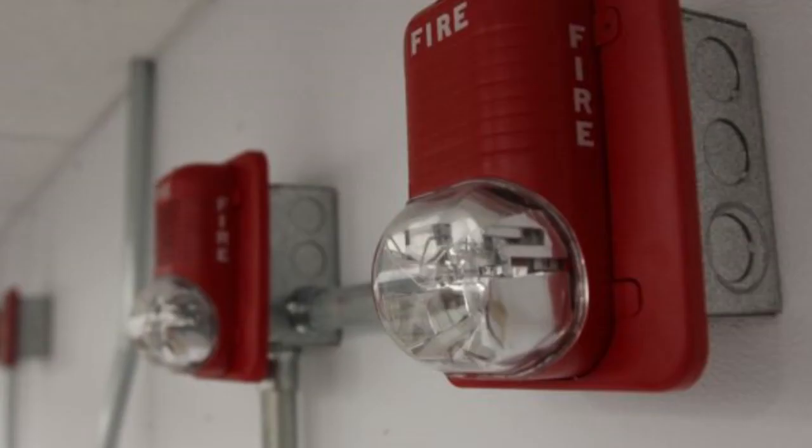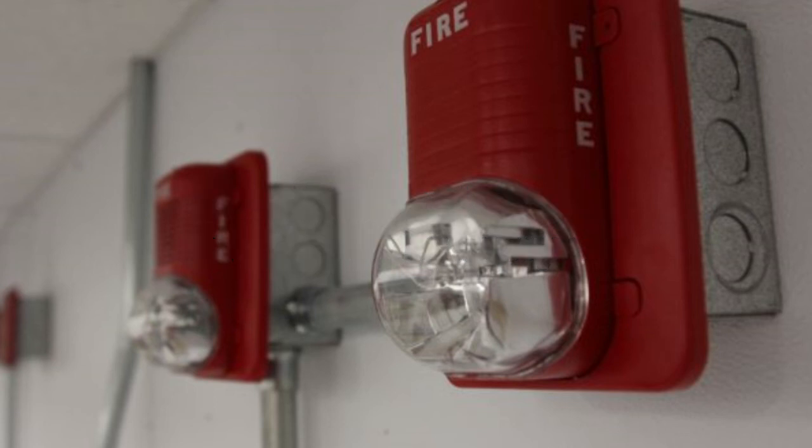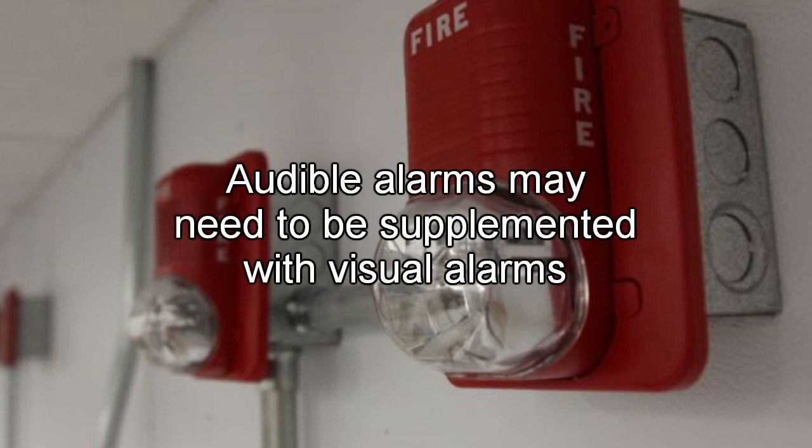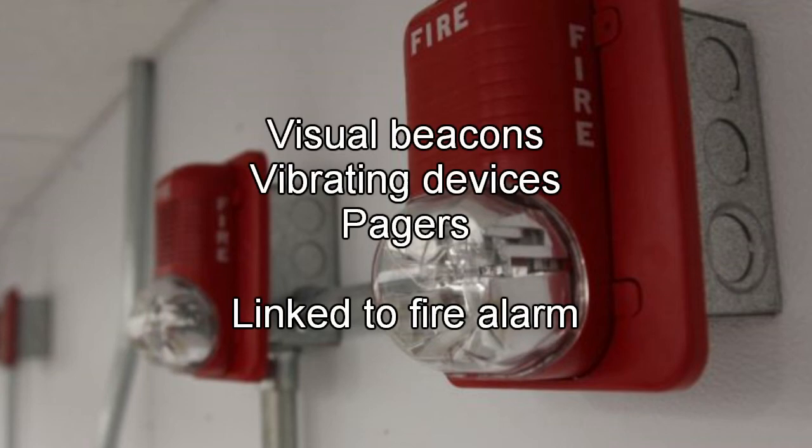The fire warning sound level should be loud enough to alert everyone, taking into account background noise. In areas with high background noise or where people may be wearing hearing protectors, the audible warning should be supplemented, e.g. with visual alarms. Where people have hearing difficulties, particularly those who are profoundly deaf, then simply hearing the fire warning is likely to be the major difficulty. Among the most common solutions are visual beacons and vibrating devices or pages that are linked to the existing fire alarm.